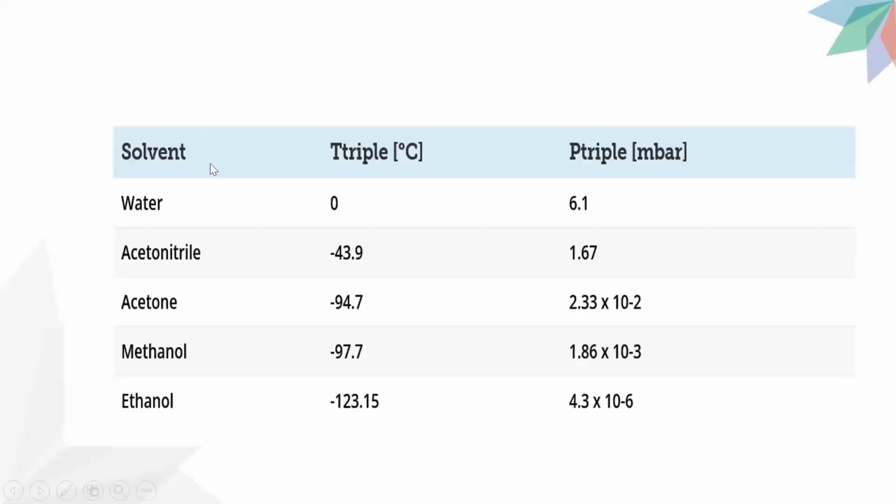From this table, you can see the triple point of water, 0 degrees centigrade, in comparison with the triple point of other organic solvents. These organic solvents are characterized by lower freezing temperatures, so they require refrigeration designs to provide the lower temperature to freeze and condense them, as they may cause damage to the vacuum pump or to other parts of the freeze dryer.